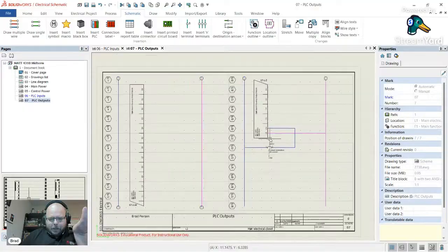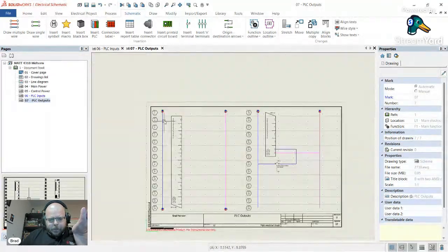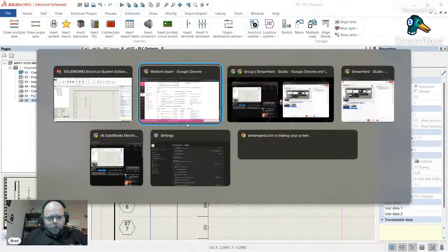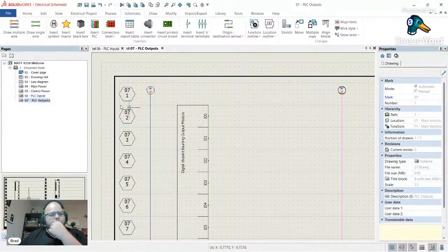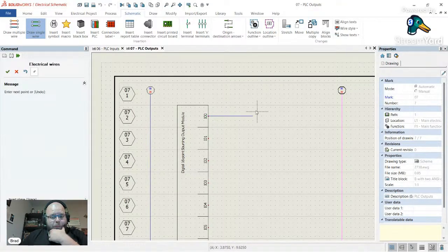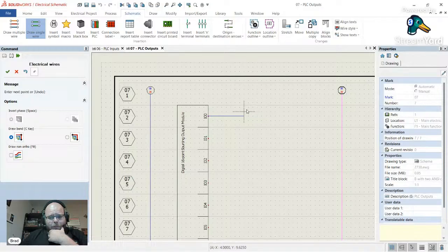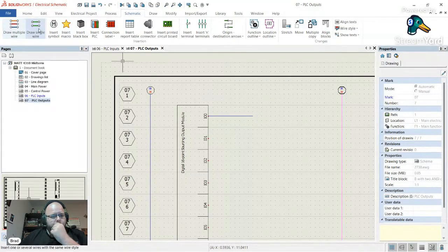So the card's powered. The card is powered. So let's see. Oh, solenoid valve. Yeah, I'll do that. And then, well, no, I want to do both. I'll do these first three, and then hopefully by that point, we can sort of call it a stream. So coming out of it will be 24 volts since this is sourcing outputs. It'll be 24 volts. So these are blue wires. Don't forget that, blue wires. So like sort of kaboom, right? These first two